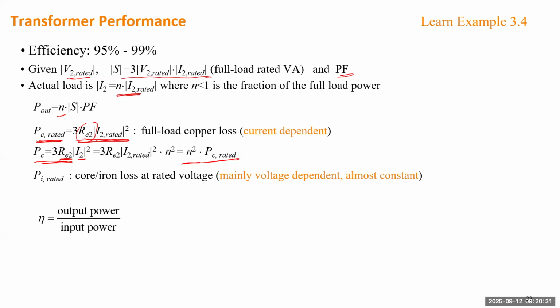Even if there's some room to use a transformer to control voltage, as we discussed in the later slides, usually the voltage can vary in a very narrow range. So it has to be close to the rated voltage levels. But current can change largely from maybe 0 to a fully loaded current. So the iron loss doesn't change a lot. It will be roughly the same value.